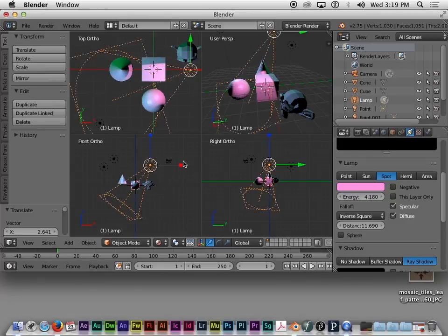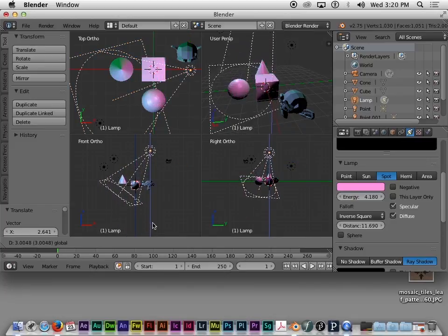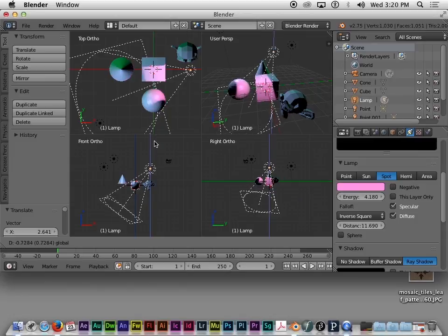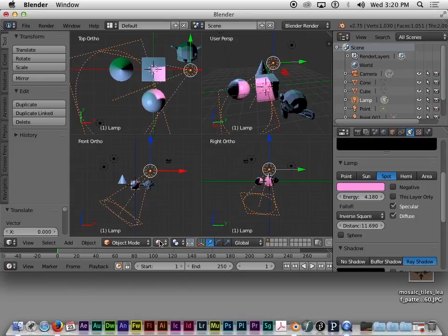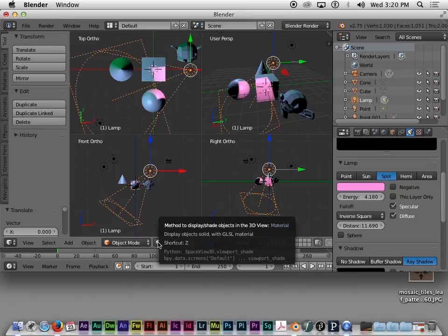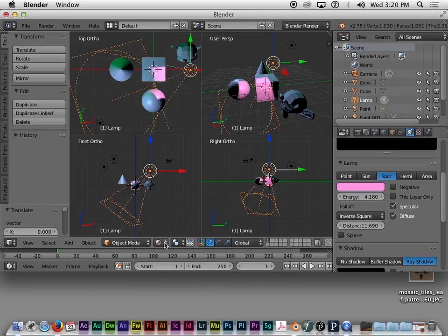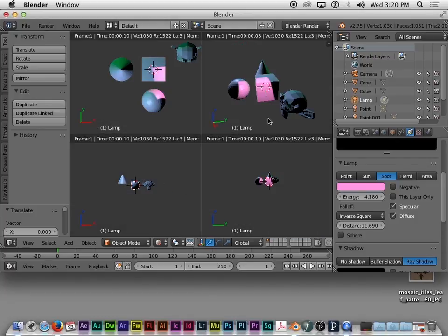And again, as you work with the tool in the environment, manipulate the lights, position them, and work with them to get the effect that you want out of your scene, putting them close or near or far. If you want to render your scene in a higher quality render, you can also switch the shader option at the bottom of your 3D menu, where it's probably an orange sphere right now. You can switch that to where it says rendered. That will give you a temporary on-screen, low-level preview of what your final output will look like.